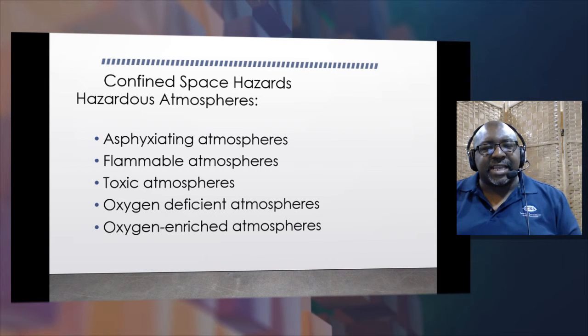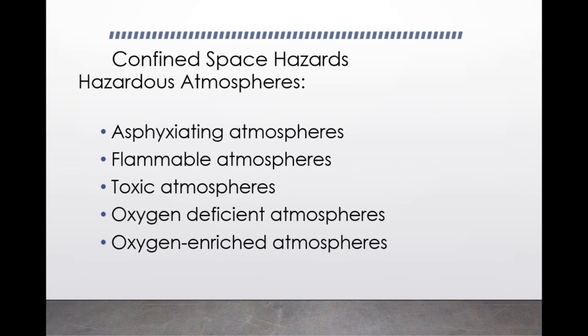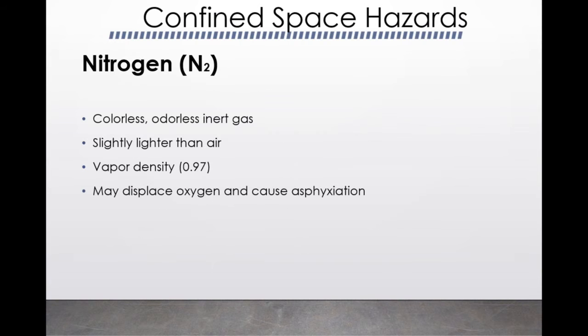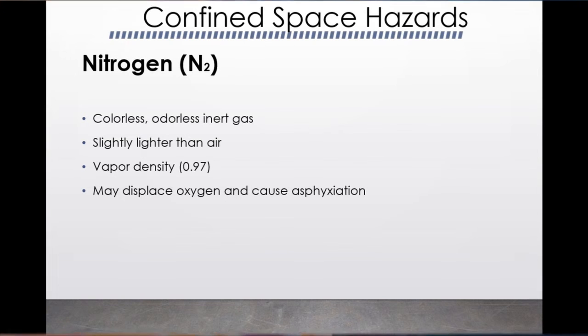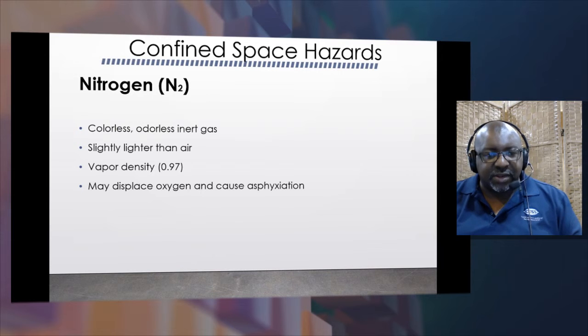So your confined space hazards for your atmosphere could be an asphyxiating atmosphere, something that's going to cause you to suffocate. Flammable, which could cause a fire, obviously. Toxic, and oxygen deficiency, oxygen enrichment. So those are all the kinds of atmospheres that you're going to have. Specifically, you might be exposed to nitrogen, which is a colorless, odorless, inert gas.